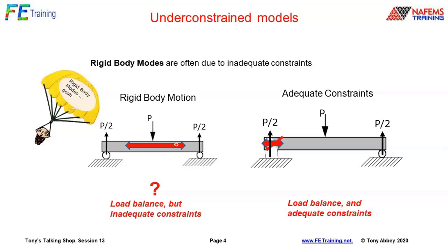This is, I think, the major source of frustration. The loads I'm applying are in balance, and I can see my reaction paths. The trouble is FEA is being really picky and pedantic in saying, okay, we've got load balance, but we've got inadequate constraints. It's actually assembling the system stiffness matrix, then partitioning out the constrained degrees of freedom, and looking at that matrix to invert it. That's the mathematical explanation. So it doesn't actually care about the loads. If you put the loads on in balance or not, it hasn't put the load set on at that point. It's just looking at the conditioning of that matrix.